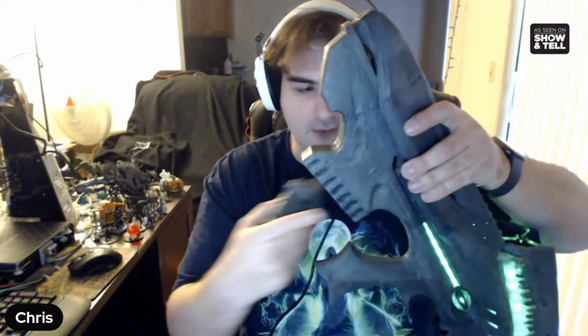I can actually take out the cartridge. See? Look at those magnetic connectors. Yep, I used a 5-pin magnetic connector. 3 of the pins are for extending the LED strip. 1 of the pins is for charging, because I can actually charge this through USB-C. And the last pin is for reloading. I'm grounding a pin, so when the cartridge is out, the pin is open. Then it's reloaded.